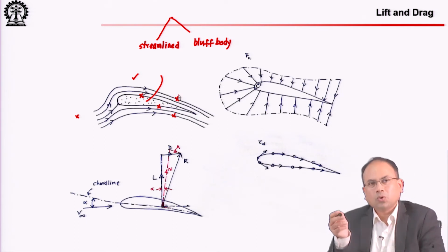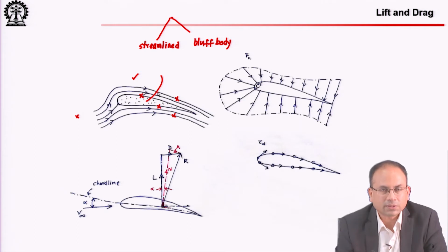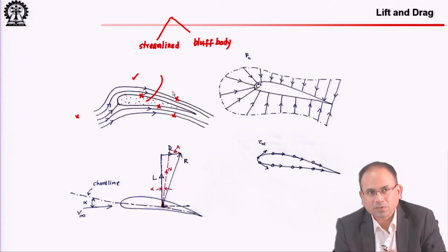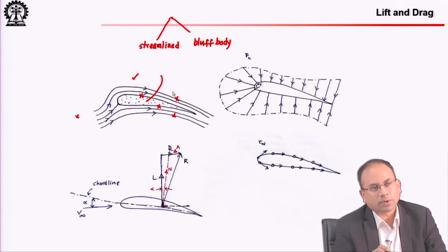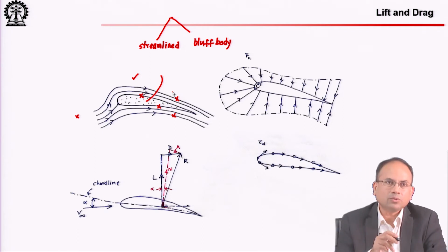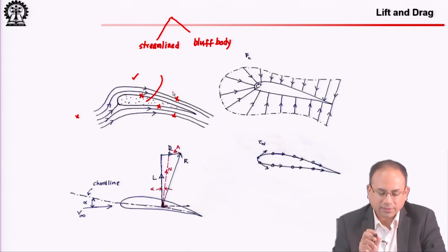As long as you know either pressure or velocity, you can find the other one. So, if you know pressure at these points, you can find the velocities. If you know the velocities, you can find the pressure using Bernoulli's theorem. And right now we are talking in detail about Bernoulli's theorem, and we will talk about the restrictions under which it can be used, it cannot be used, where it can be used with a little bit of consideration, etc.